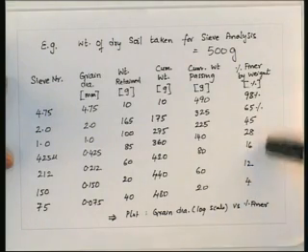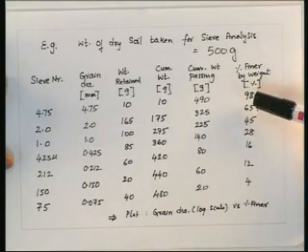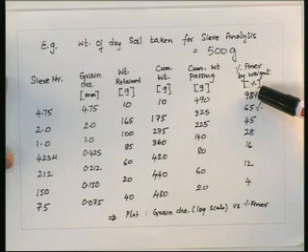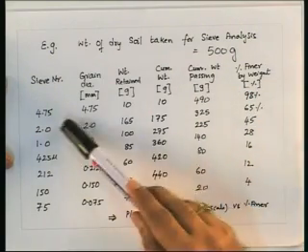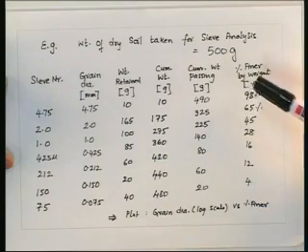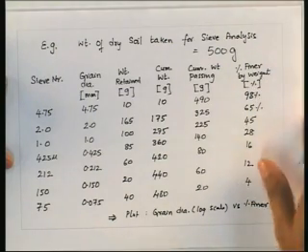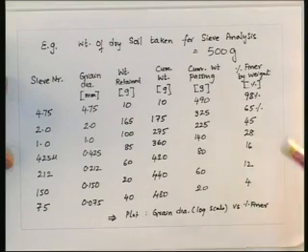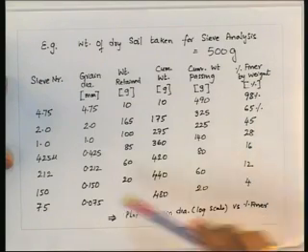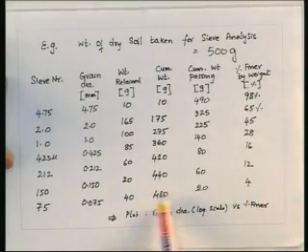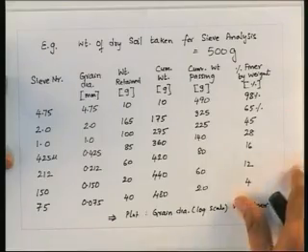This indicates that 98% of the particles are finer than this 4.75 mm size. That means only 2% of the particles are coarser than this size. So, once we get the percentage finer and grain diameter, we can get the grain size distribution curve.